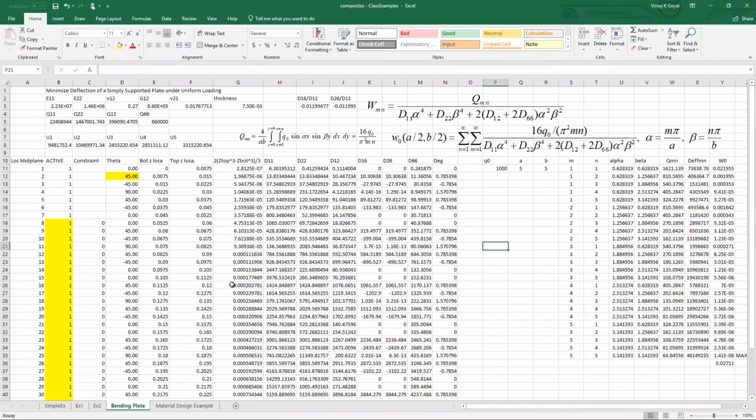So this is a little bit of a messy spreadsheet, but I think it's going to help us understand how this was done. Like, what if we select a square plate? Then what are the optimal ply angles I need? And so here you can see this constraint here is that B17 minus B18 right now is 0 because the two consecutive values are 0. But let me illustrate for you. If I make this one inactive, I'll have a -1, and the constraints are written so that all of this has to be greater than or equal to 0. So you cannot have an empty ply in between.